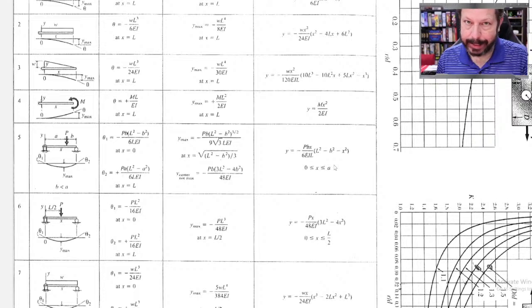So it kind of depends, but with this one we're looking at right now, you can't even put in values that would calculate the deflection on the short side of the beam. It tells you that x starts at 0 and goes to a. That's also how they show it in the picture here, because you can see the y-axis starting on the left-hand side.